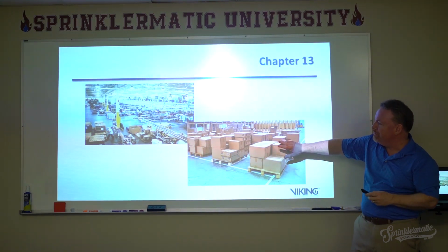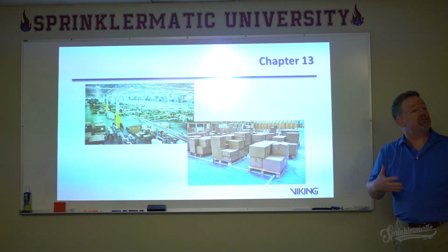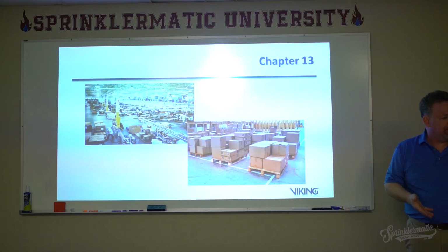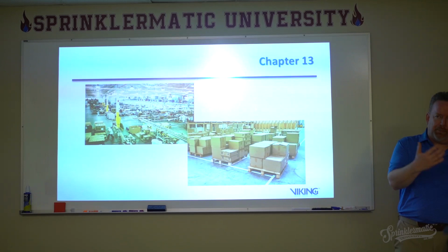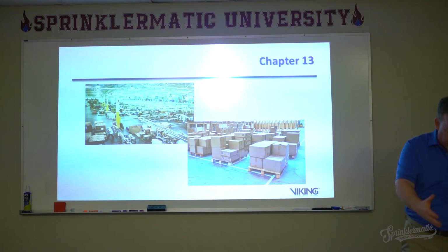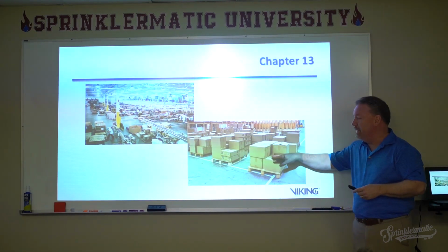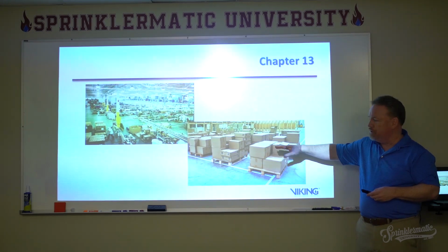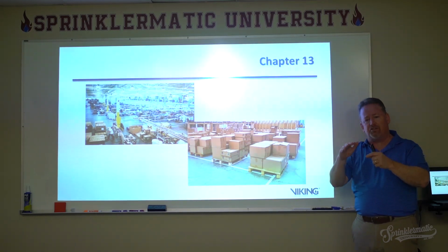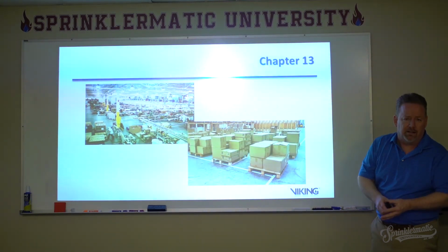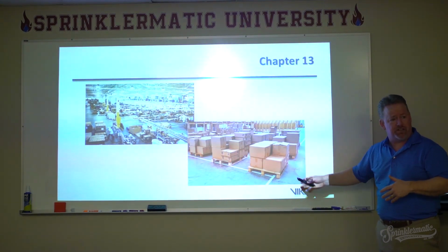However, you do have certain warehouses that are storage. That's what they do, but they don't store above 12 feet. So what it becomes is what over the past editions was called miscellaneous storage, and it was kind of limited to this one particular area, and we'll talk a little bit about that in a moment. But now it's also got low piled storage. So this is a warehouse. It's not anything else. It's not anything that can actually be defined as an occupancy hazard classification per se, but it is a storage application.